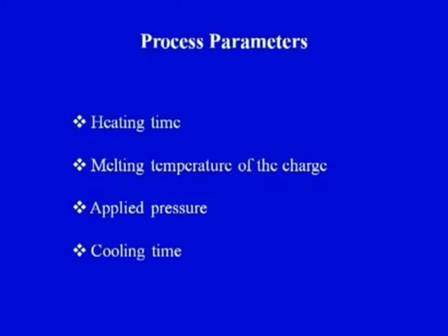The plastic which was at elevated temperature is now slowly coming down to room temperature and getting the final shape of the product. So for how long the two mold halves or the two die halves should remain closed is also very important, and that can be called the cooling time. So the cooling time is also equally important.